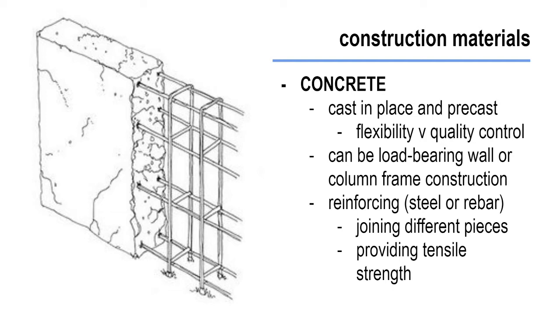So if you have about 0.4 or 0.5 amount of water is really good for foundations. Too much water is going to mean that you have too much space between those different particles that make up that concrete mix, which will make your cement or your concrete weaker. But this mix amount can vary and cause the concrete to have different properties, whether it be visually or structurally.